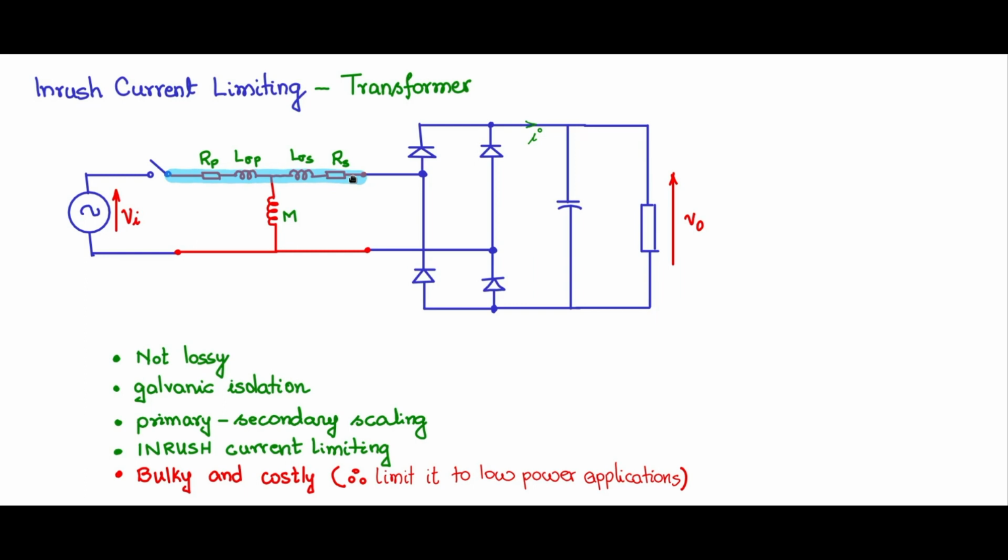And all these impedances, if I take M very large compared to all these impedances, there will be a very small amount of current, magnetizing current only, that will flow through this, and all the load current will flow through in this fashion. So all these impedances will act to limit the surge current. So that is the logic. So if we take M very large compared to L sigma P plus L sigma S, then if we say the voltage across this leakage inductance is VL, then by Faraday's law you have VL is L sigma P plus L sigma S dIn by dt.